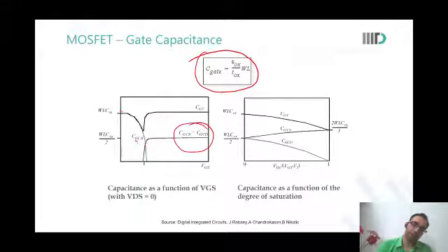Great. So this line is the VT point. You see, already this capacitance has started to rise before that. What does that mean? The inversion layer is forming due to the source and drain. So the lower graph is basically elaborating the components.